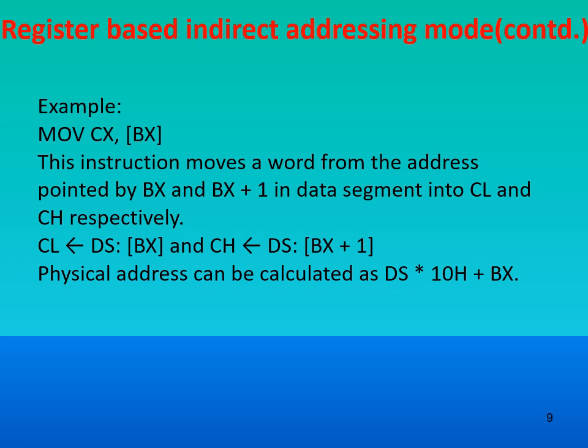So you know that your 8086 is byte addressable. If you go to that effective address of BX, whatever it is, we will be getting a memory location. Since it is byte addressable, how many bits can we extract from that memory location? We can get only 1 byte, in other words, 8 bits of data. But we are trying to put those 8 bits into a CX register. CX register is of how much capacity? CX register is of 16 bits.